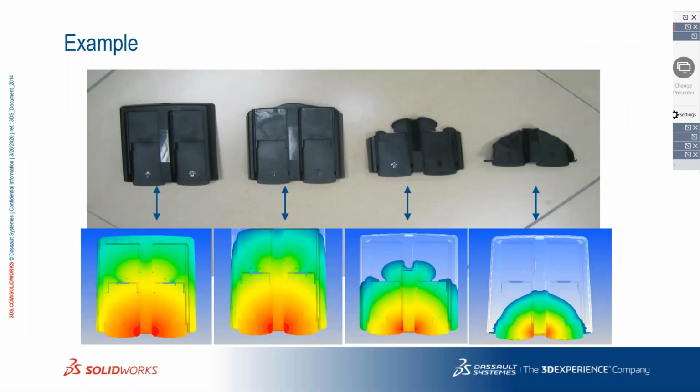When we see the examples here, this is one simple example of a short, where the first iteration was filling the part only to such a distance. After several iterations, maybe 3 iterations, virtually, not on the mold, doing the changes can result in avoiding the short.